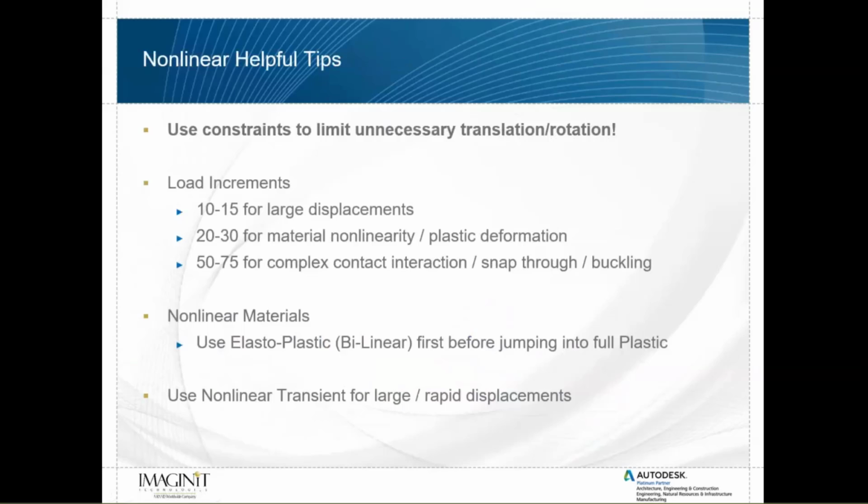Before we get into our demo here, I wanted to give you guys some helpful tips that are really important when you start running a nonlinear static analysis, and some things you might run into when you do. The most important thing, and the reason I put this in bold, is that it is a really helpful tool that a lot of people don't think about: using your constraints to limit unnecessary translation and rotation. When we get into Nastran, I'll show you what this means.